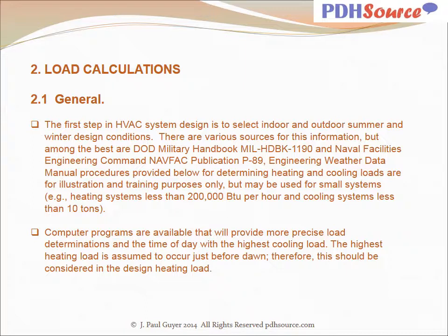The first step in HVAC system design is to select indoor and outdoor summer and winter design conditions. There are various sources of this climate information, but two that are available, and they are free, are produced by the Department of Defense, the Corps of Engineers specifically, and the Naval Facilities Engineering Command. These climate data publications, there's nothing governmental or bureaucratic or military about them. They're just good, solid technical guidance, and they are available free.